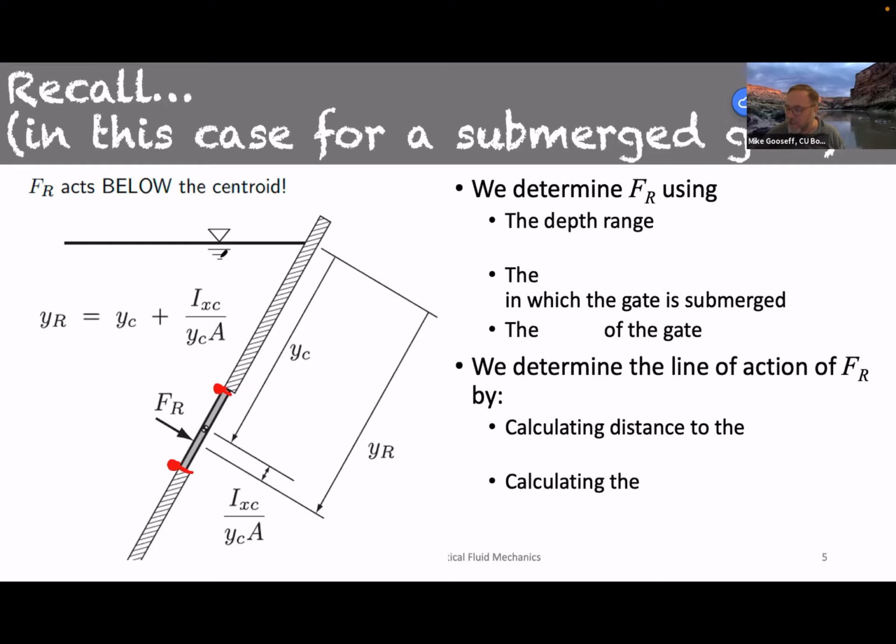Now recognize that, of course, the pressures at those two locations are dependent on the depth to get to those locations, right? So here's some H, let's call it top, and here's some H bottom, B for bottom of the gate. And what's important about those is those are vertical, right? Those depths are vertical, and you come straight down from the water or fluid surface in this case.